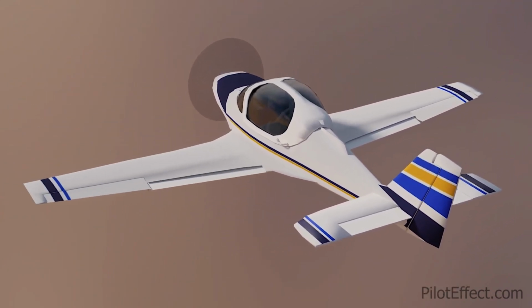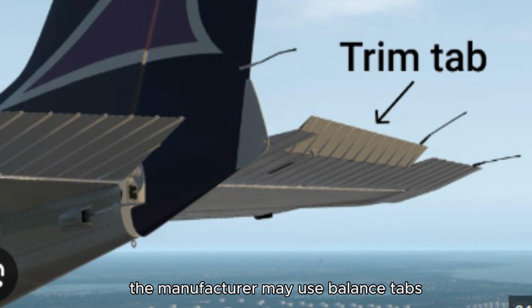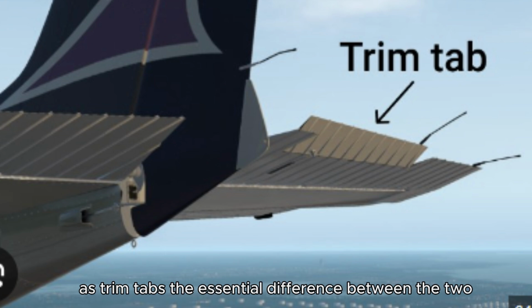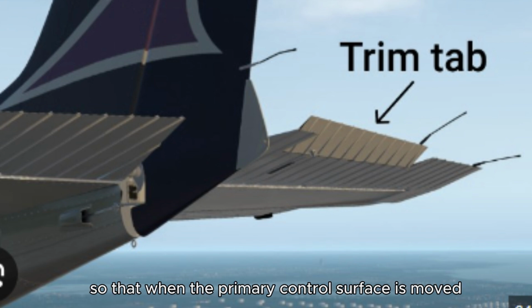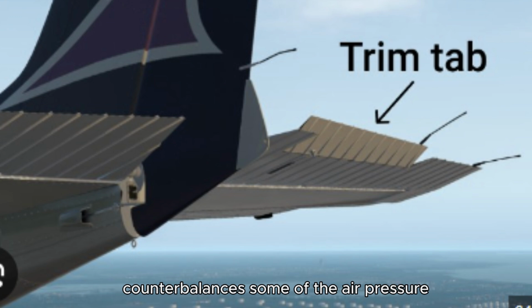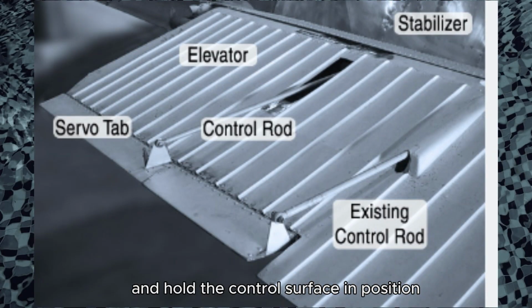Balance tabs. The control forces may be excessively high in some aircraft, and in order to decrease them, the manufacturer may use balance tabs. They look like trim tabs and are hinged in approximately the same places as trim tabs. The essential difference between the two is that the balancing tab is coupled to the control surface rod so that when the primary control surface is moved in any direction, the tab automatically moves in the opposite direction. The airflow striking the tab counterbalances some of the air pressure against the primary control surface and enables the pilot to move the control more easily and hold the control surface in position.